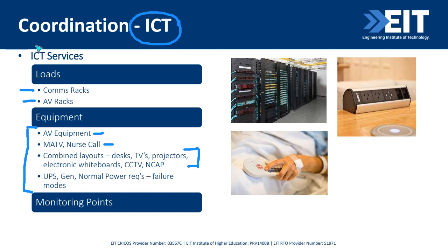Because comms is often very important, we need to have a discussion around what happens during a loss of power. Can their equipment go down? Are they providing their own backup battery within the racks? Or do we need to provide a UPS supply? Do we put it on generator or not? How important is it? There's a few questions to ask around that scenario of loss of power.